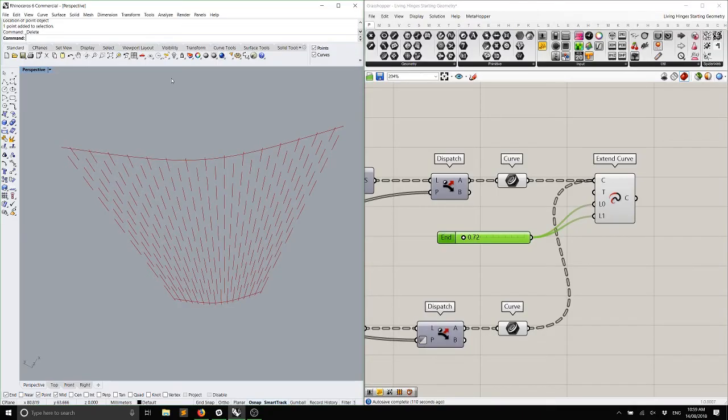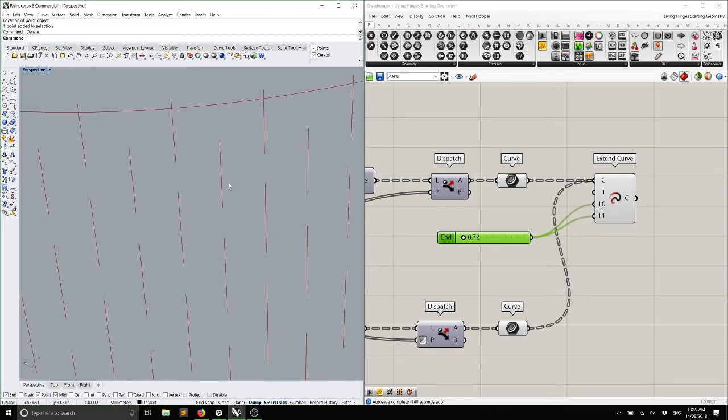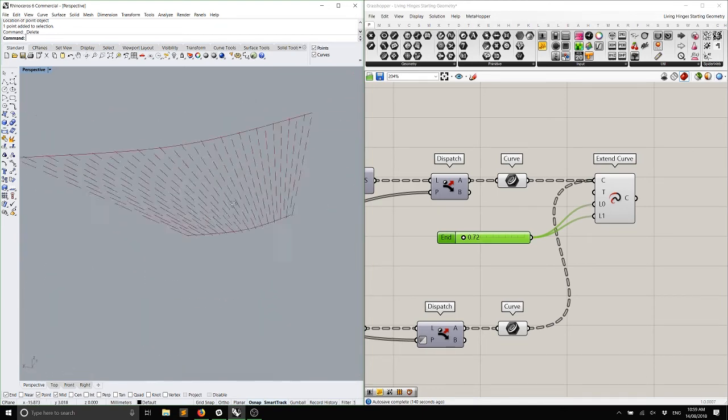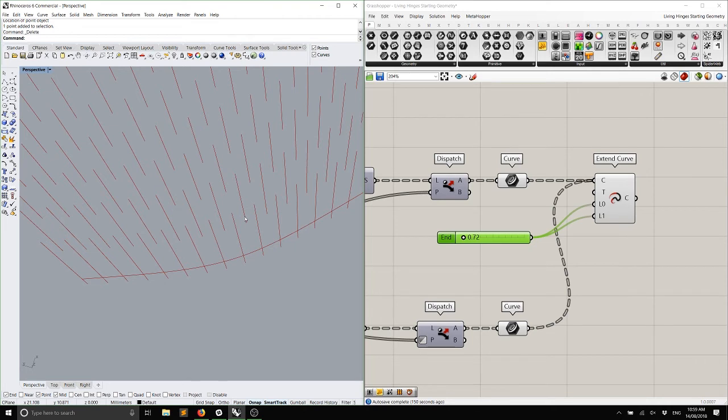Yeah, so what we're doing here is we're relying on the width of the laser, and depending on the machine that you use, normally laser cutters are prided on how thin their laser is. So it might be like 0.2 mil thick cut, okay? So we kind of want to actually encourage these to be a little bit wider, okay? And this is the dangerous bit, right? Because the width that we make something up here, if we then look at it down here, it might end up completely destroying the cut, okay? So just be careful with that.